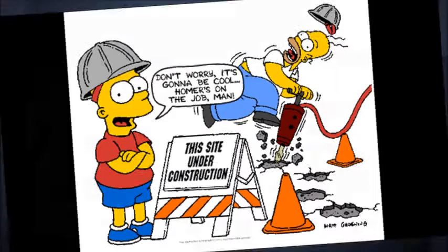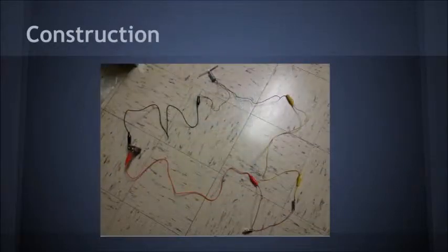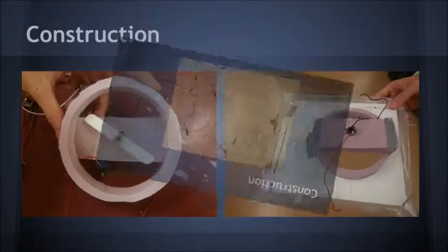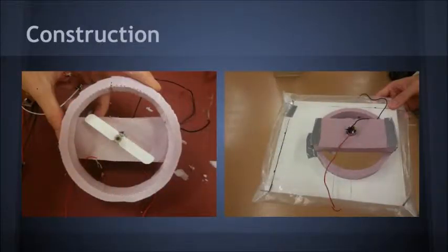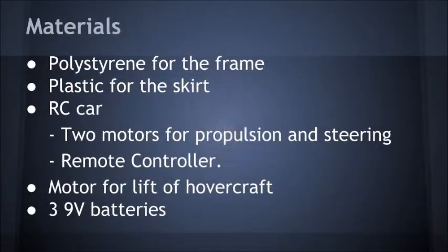So basically our hovercraft is designed to float on a cushion of air that has been forced under the craft by a lift motor. To help the lift, we cut 4 small holes on the bottom of the skirt that is attached to the body frame. The holes are located in the spots that touch the ground when it is inflated to balance the bottom pressure. An air chamber is also designed to trap the air inside the skirt to provide lift force and reduce waste energy.